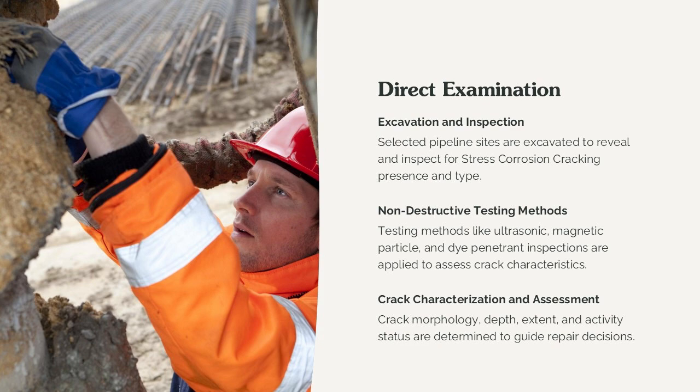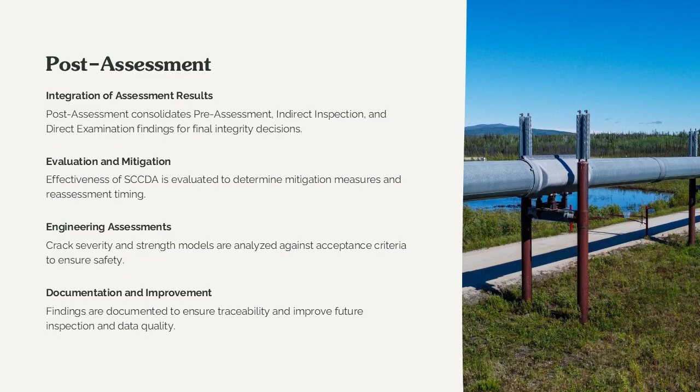Direct examination provides the ground truth necessary to validate assumptions made during earlier steps. The findings from this step are critical for determining immediate repair needs and for refining the overall understanding of SCC susceptibility along the pipeline. Post-assessment integrates the results of pre-assessment, indirect inspection, and direct examination to support final integrity decisions.